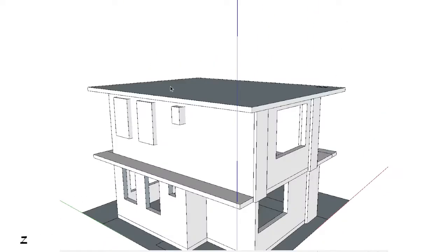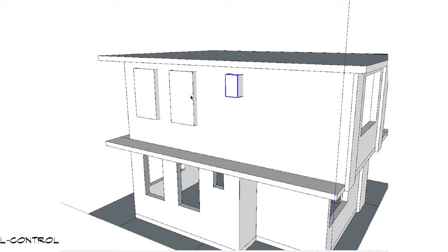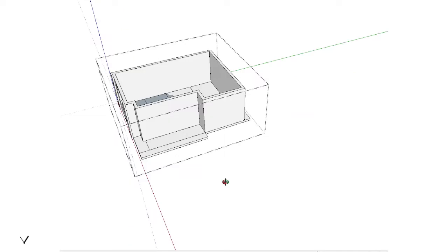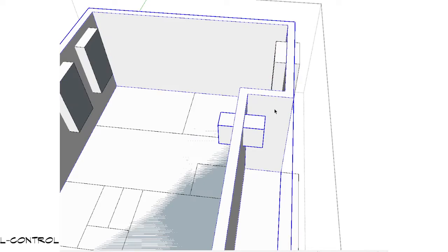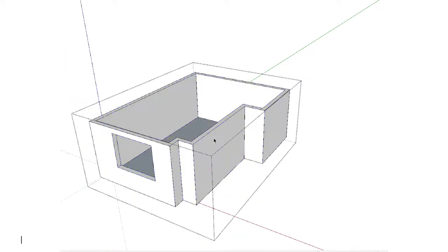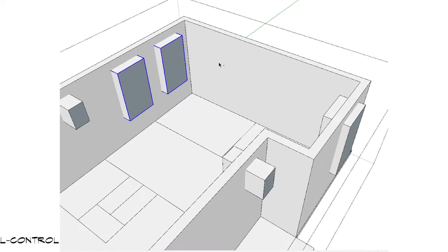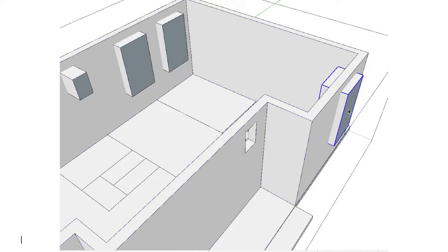Alright, so go back to 3D and let's see. Now whenever we go back to 3D, it goes to this camera view, so I want to Shift Z and make this my default 3D view. Update, okay? We still have these window openings, so let's go inside and use our Shift subtracting, okay? Have to remove this. Now I'm curious if I could use 2 to subtract at once. Doesn't work, so it has to be 1 at a time. No problem.